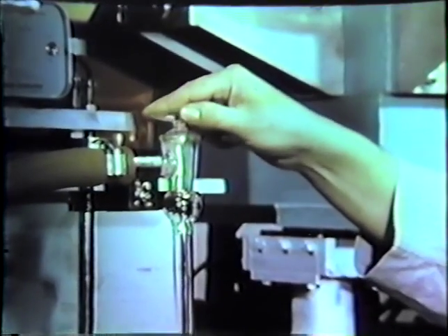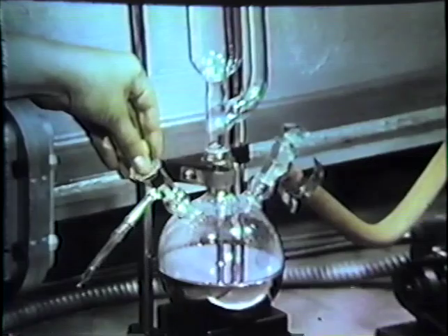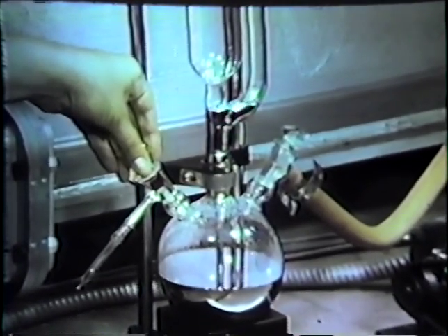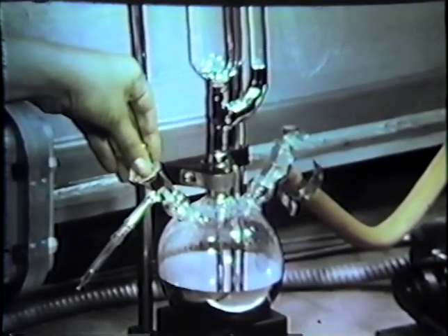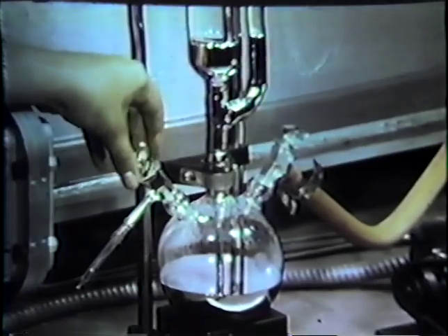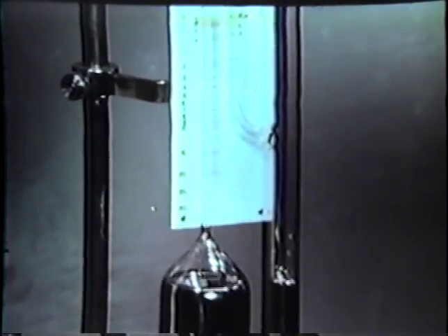A sample of the gas to be measured is admitted to the gauge. This sample will be trapped in the capillary tubing by the rising column of mercury. Since a sampling technique is used, it is not possible to obtain continuous readings with this type of gauge. Also, remote reading is difficult.